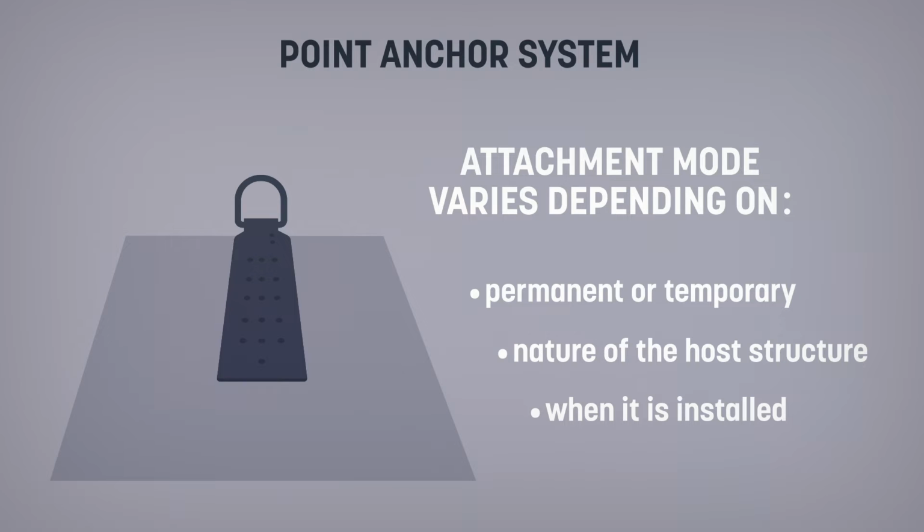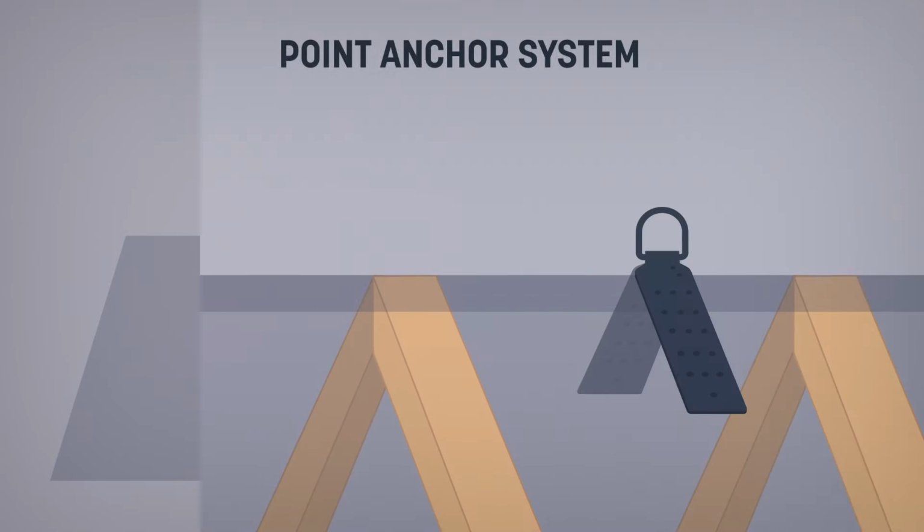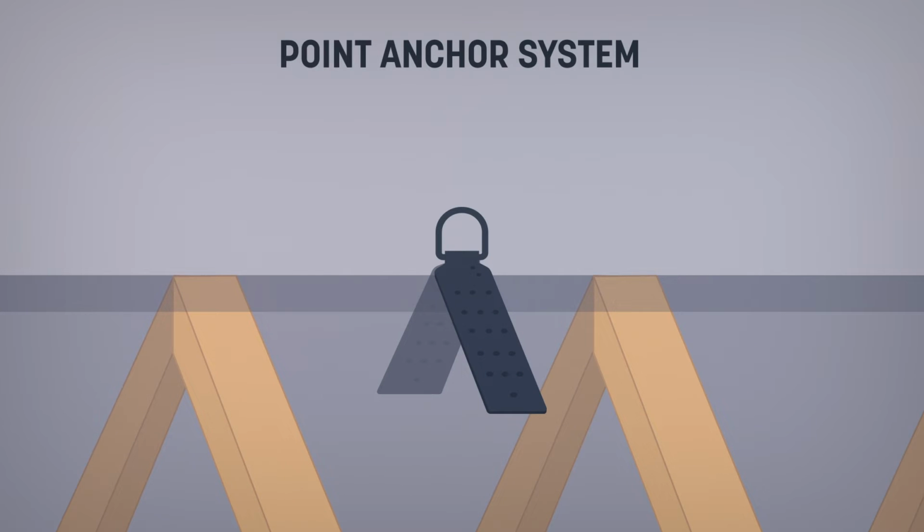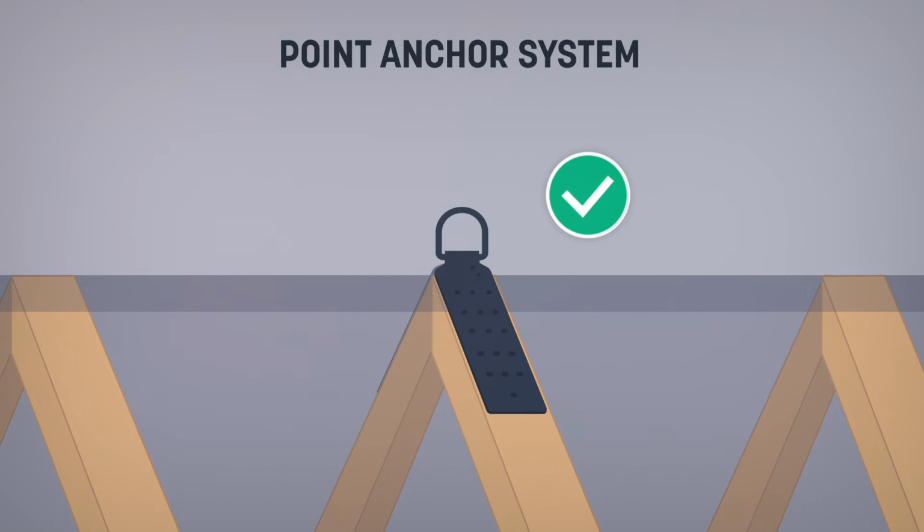To ensure the strength of the system, always refer to the manufacturer's manual to know the proper installation and the required attachments. The host structure must be capable of supporting the additional effort brought by the anchor system. That's why it should never be placed between two roof trusses. It must be on a roof truss.